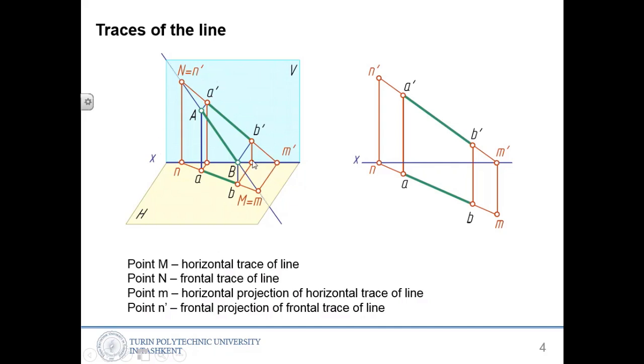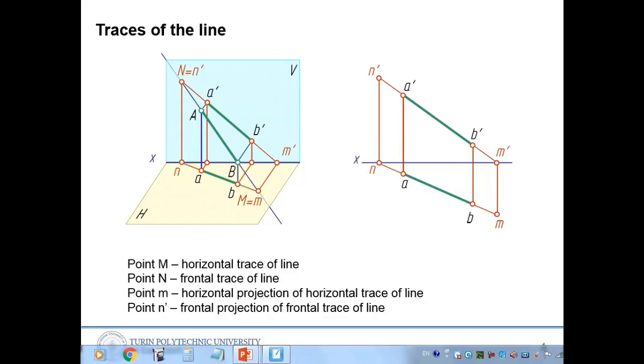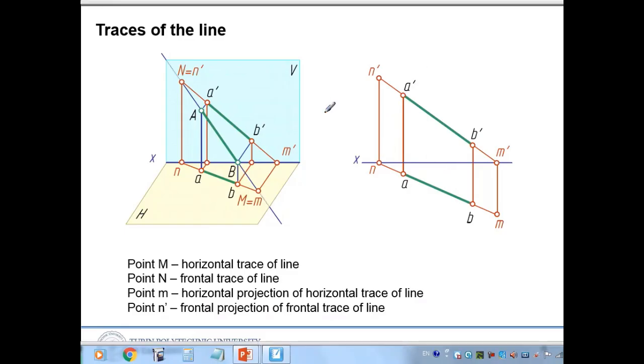So the way in two-dimensional space is the same. We make a line and find a point N on the OX and M dash on the OX, and we make a line until it intersects this AB projection. So we can find M, and on this side we make a line and find the intersection point N dash.